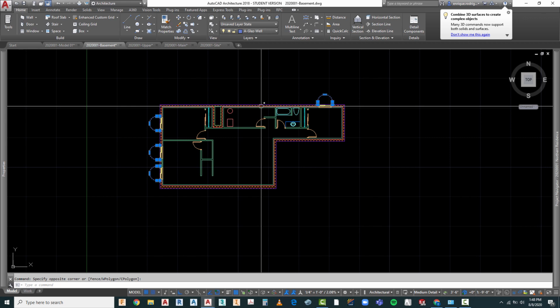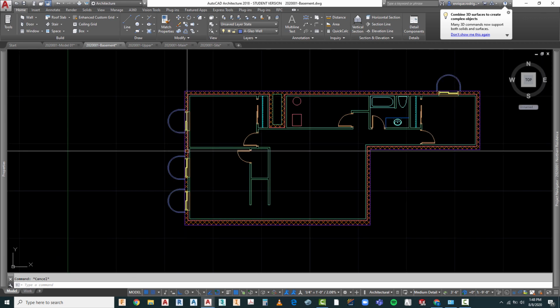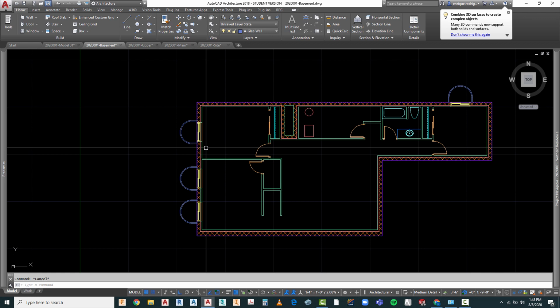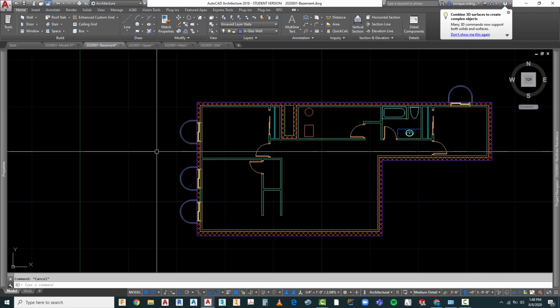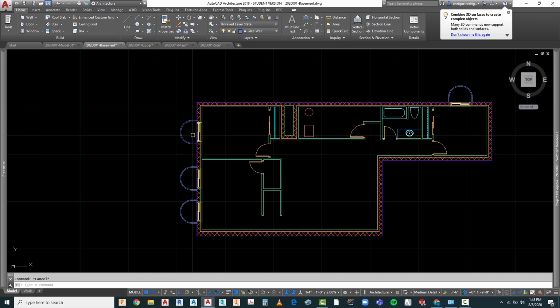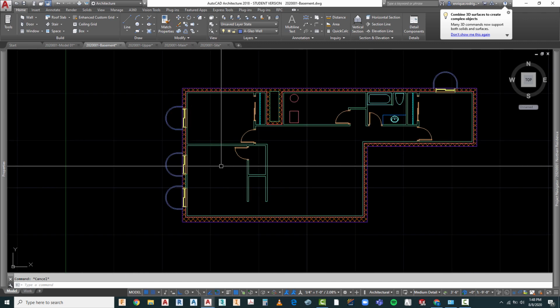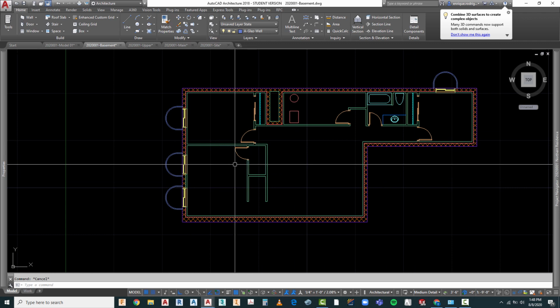into the site construct. I don't like that method, mainly because if we make a change to the design of the window well, we would then have to modify it and bring it in again and do some extra work. I think the easiest way is to understand the principle of draw it once and then be able to manipulate either layers or XREFs or X-clips, etc., to only show the parts that you want to show. And I will show that in a later video once we create our final sheet and we bring in all the XREFs together to show what we want to do.